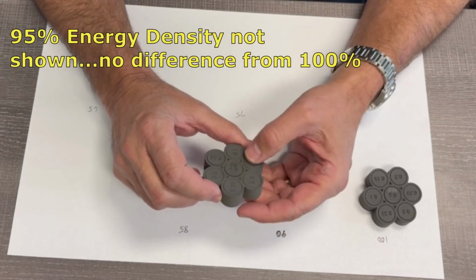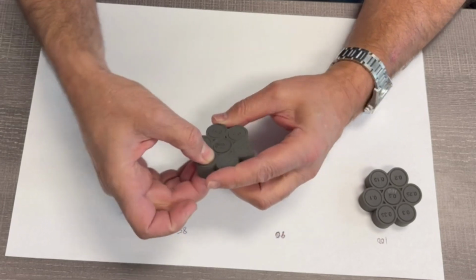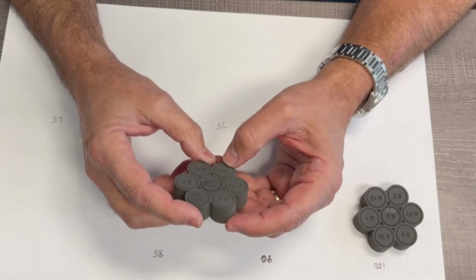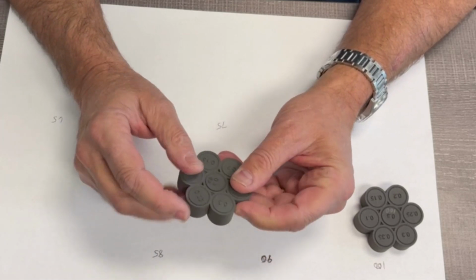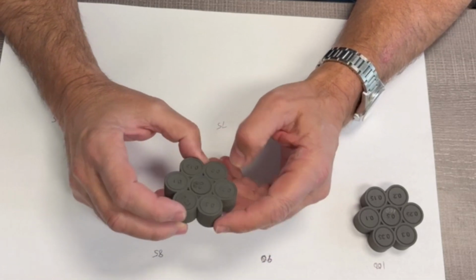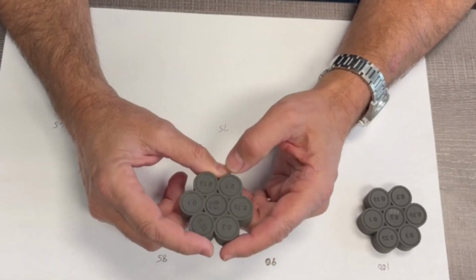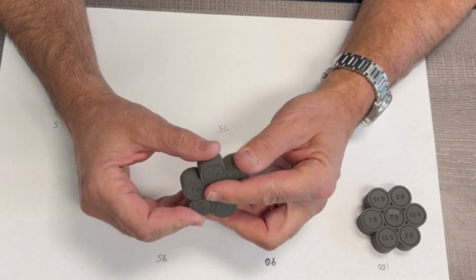So then I did a 90% as well. Obviously the center one moved there, and the 0.35 actually started moving there. Then I tried to crank on the 0.3 and it just would not budge. So we got improvement by lowering our energy density. I'll show you a wrap-up on a file here with the results from everything, including dimensions and densities. But just to give you an idea, I actually saw decreasing density of the model as I decreased the energy density, which makes sense.